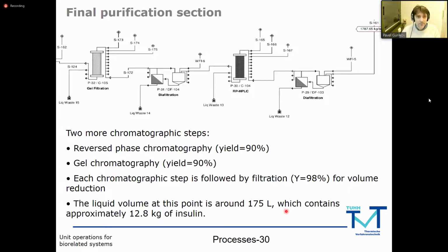That's why we have a series of chromatography units, and after each column we have a process very common to us, called diafiltration. We combine dialysis and filtration here. We filter through a dialysis membrane. We don't wait until low molecular weight compounds diffuse through the membrane, but we help them by applying pressure, creating a pressure gradient along the membrane.